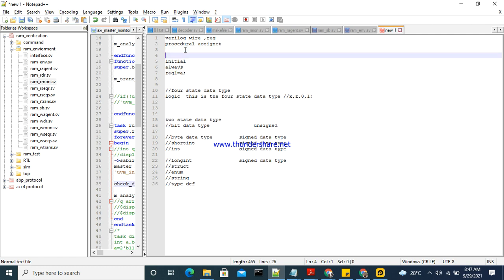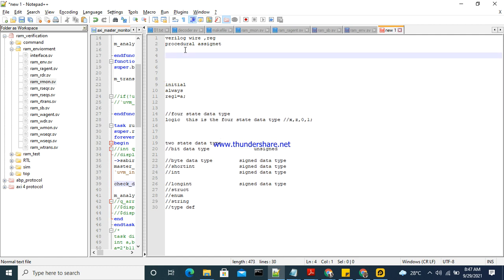And we are using the continuous assignment statement, right? The continuous assignment statement means assign. That assign comes under the continuous assignment statement. So assign wire1 = b. The left-hand side variable inside the continuous assignment must be a wire data type. This is the rule of Verilog. If you violate the rules of Verilog, then it creates a problem in your programming.